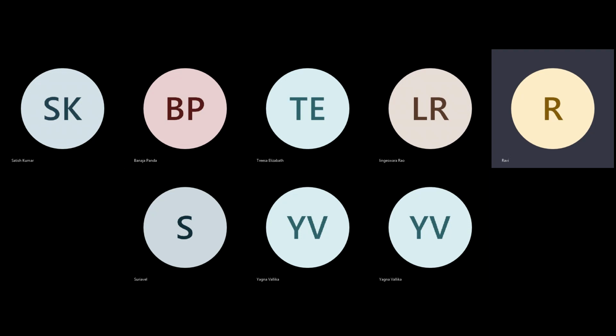Now for each net, the pitch in metal 3 or metal 4, you have to multiply accordingly. So let's say the pitch is about 0.5 micron. So 0.5 into 230 nets, that should be your total channel distance.